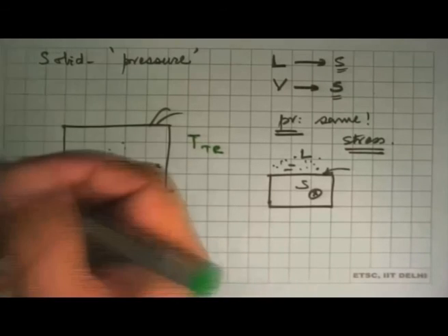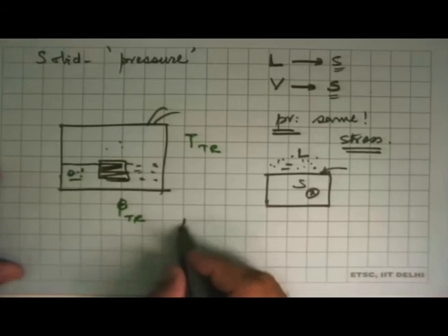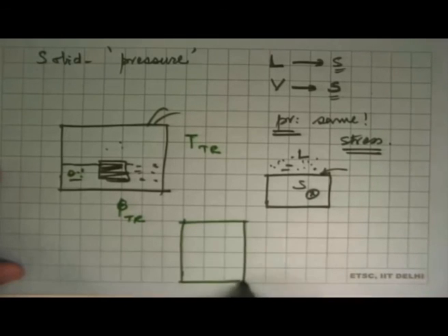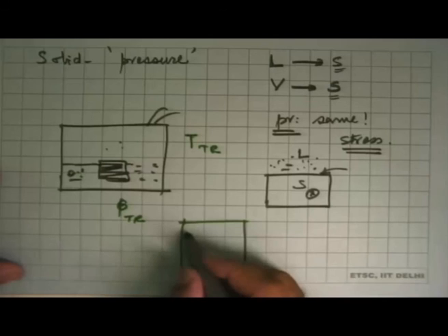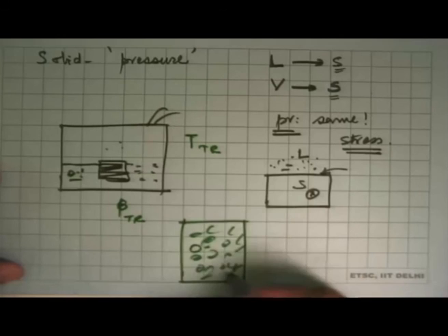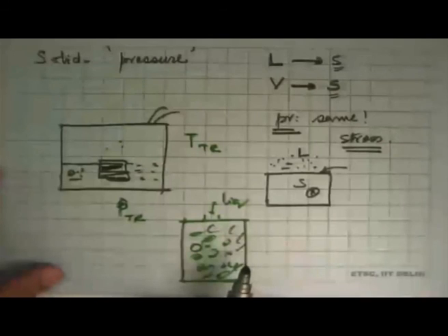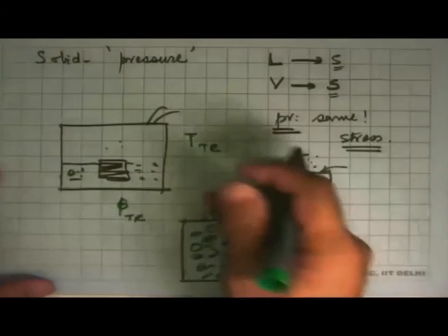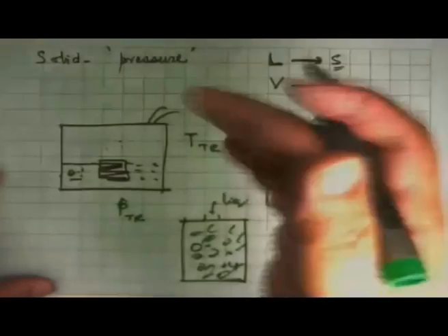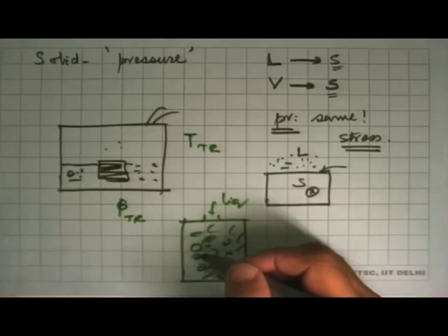And we exploit this in one very important way, not in thermodynamics but in all measurements of temperature, especially in heat transfer. What we can do, and you can do this small experiment yourself, is take a thermos flask, push crushed ice into it, pack it as much as you can, and then pour a little bit of tap water in it. What will happen? The temperature of the water, which was say at 25-30 degrees Celsius, will go down, some of the ice will melt, and if you keep measuring the temperature by putting an instrument in this, you'll see the temperature going down. It will start going to 3 degrees, 2 degrees, 1 degree.